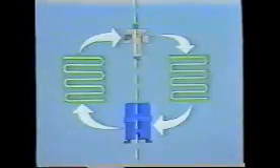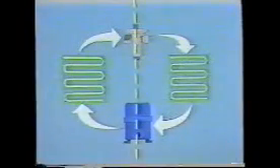As you know, the evaporator is located in the low pressure side of the system. It's the place where heat is absorbed from the surrounding air or water by the lower temperature refrigerant inside the evaporator. As the refrigerant absorbs heat and vaporizes, the air or water is cooled. Because the refrigerant is at a low pressure in the evaporator, it vaporizes at a relatively low temperature.